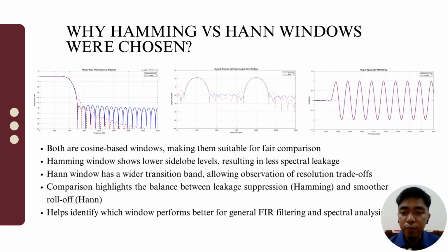If we go deeper into this figure, at the first band section, we can clearly see 0 to 1000 Hz at the cutoff. Both filters successfully pass. Second, at the transition, we can see that at 1000 Hz, both filters sharply drop off. And the last one is the stop band.